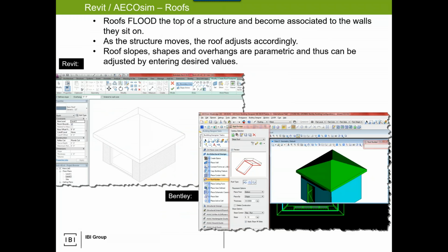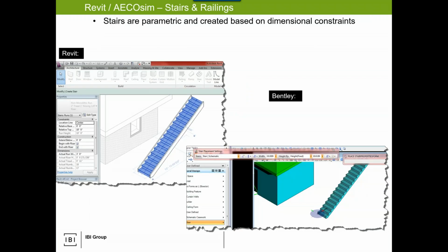Roof tools, again, very common. And the beauty about stuff like this is I hated drawing roofs and working out roof slopes, especially when you have intersecting geometries. Here you're selecting that top level, assuming this is one level. You punch in your parameters, your overhangs, your slopes, all that good stuff. Is it a hip, a gambrel, mansard, whatever, and away it goes. It'll move with the components. It's all interconnected. I don't want to make it sound simple, but it makes life quite simple when you're able to do this.